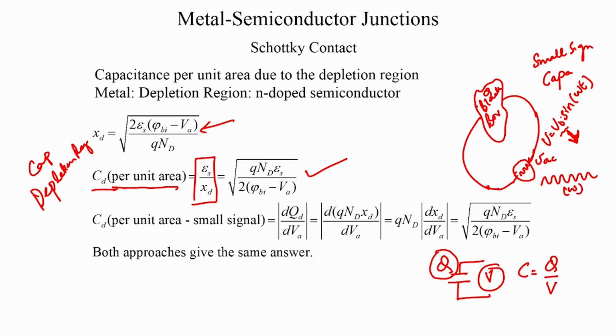And this charge is going to fluctuate in response to this applied voltage. Because of this applied voltage, you are going to see an effective fluctuation in the charge inside the device. So, that is dV applied and that is the dQ, the fluctuation in the charge. We know what we are applying here and we can measure this fluctuation, and therefore, the small signal capacitance is simply dQ by dV, and in our case, since it is the depletion capacitance, it is dQd by dVA.